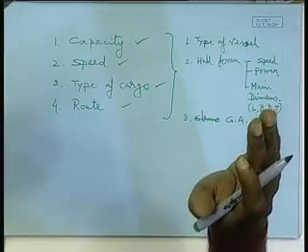Also, you will show the location of the main engine, though the final engine may not have been selected by that time, but you have a fairly good idea of the overall dimensions of the engine. So, you will have to see whether that engine fits there, length, breadth, height, all those things. What would be the other auxiliary engines and machineries. So, all these go in the general arrangement.